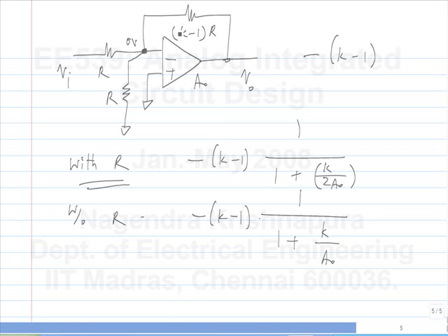What is the loop gain here? What is the feedback fraction here? K by 2. Why? What is the feedback? I mean, how do you evaluate the feedback fraction? You disable the input and you apply something to the output, see what comes back, okay, with the op-amp removed. What is that? It's a simple voltage divider, right? It's R by 2 divided by R by 2 plus, 2K minus 1. Yeah, so, right? So, what is this?